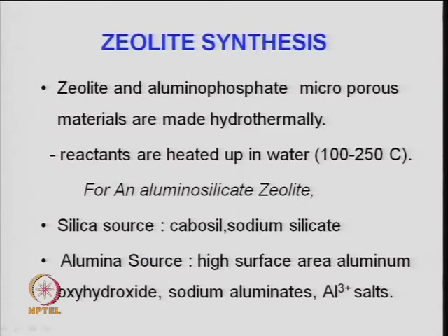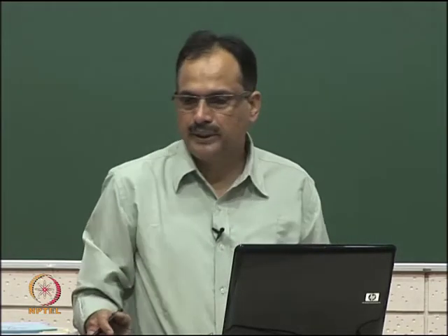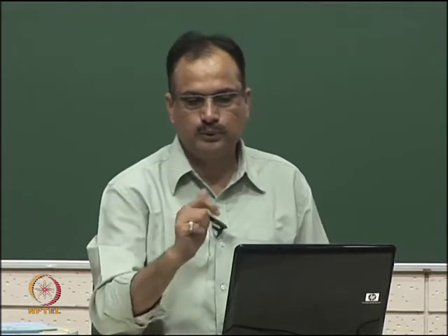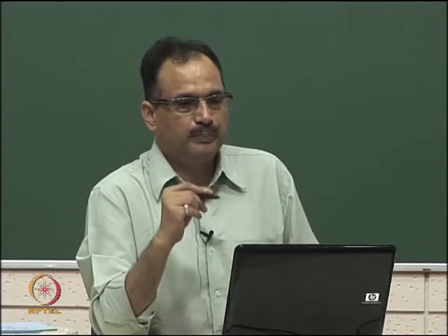So, with this background, let us come to the synthesis, because once you look at these kinds of definite structures, definite pore opening, a definite silicon to aluminum ratio, the preparation becomes a very crucial part in zeolite synthesis, unlike non-zeolite materials or other catalytic materials like silica, alumina, ceria, zirconia. For these, the preparations are well known and well defined, in terms of wet impregnation, co-precipitation, or sol gel method.